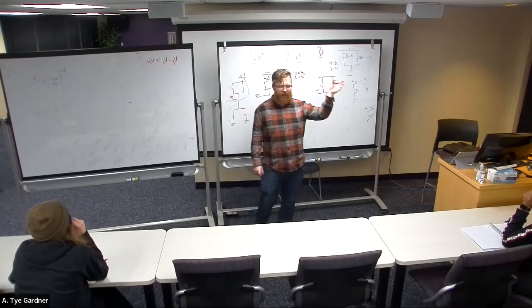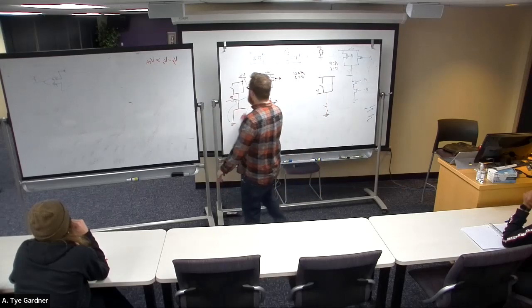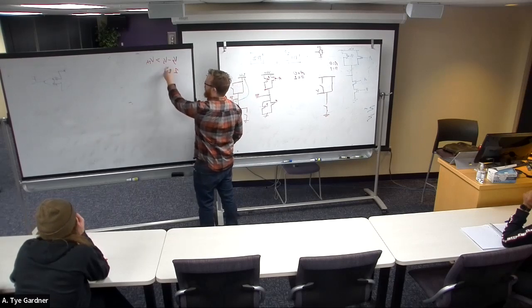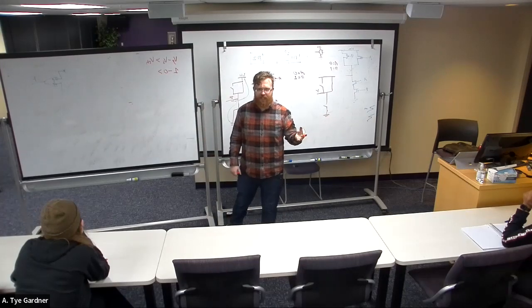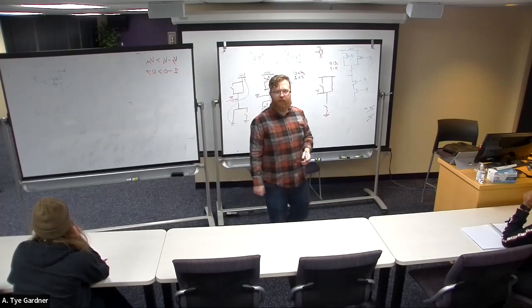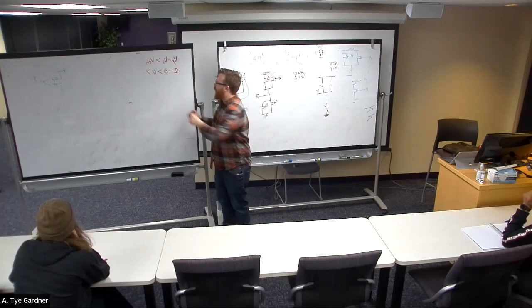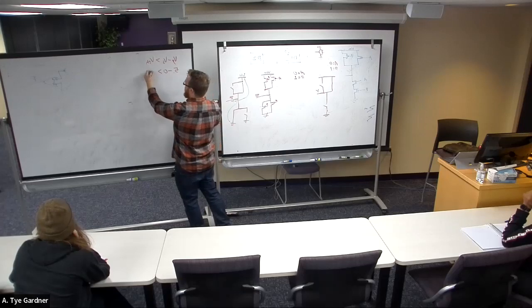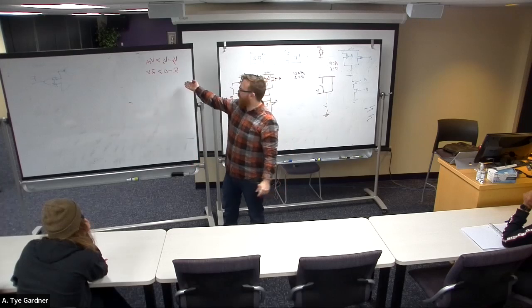We're digital engineers as far as this is concerned. We're lazy. We don't consider the analog effects. It's on or off, okay? So VG, gate voltage, if this is 1 and VS is ground, and as long as VTH is less than VCC, so let's pretend VTH is 0.7 volts, pick a number, right? 1 is 5 volts in our case, right? So it's really 5 minus, and in our case, it is probably not 0.7 volts. I mean, it could be like 2 volts. This is fine, right? 5 is greater than 2, it is on.